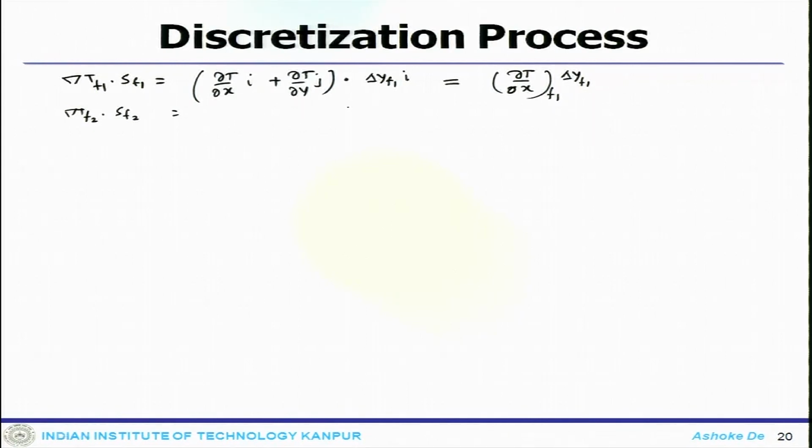Now, the point comes if you move ahead along this direction. So far we know how to get these dot products. If I get these dot products and put those equations back in the algebraic equations where all the integration is done over the faces, I can get all the components. Now, one component is still missing that needs to be evaluated, which is true for all other phases like F1, F2, F3, F4. We need to find out how to do that. Essentially it is the first derivative of temperature at phase F1.